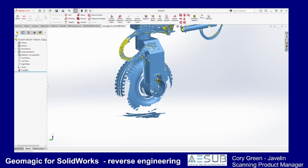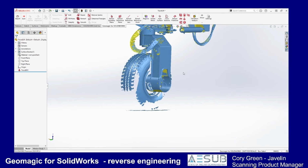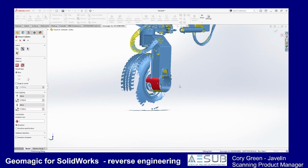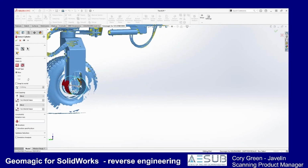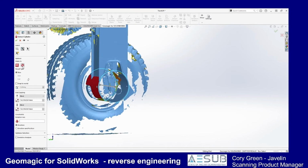This will make it easier as we move forward through reverse engineering. The first thing that we can do is begin extracting useful geometry from the model. Let's begin by extracting a cylinder from the outside faces of the hub. We'll select a couple of areas. We can do this extraction making either solids or surfaces. We can choose to orient that cylinder to the world if we're confident that the axis of the cylinder should snap to one of the main coordinate planes.